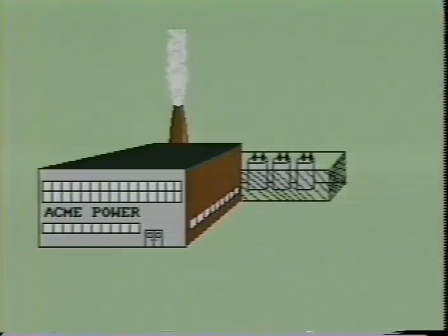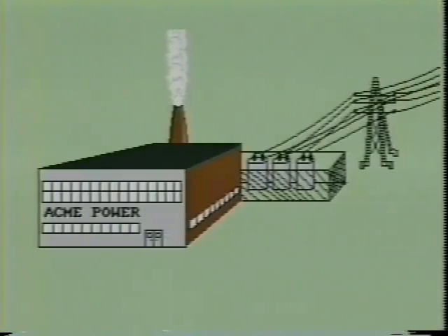For this reason, this high AC voltage is fed into large transformers to be boosted to an even greater value. These large transformers will boost the 13,800 volts upwards to 150,000 volts or even greater. This high AC voltage is then transmitted over the high-tension transmission lines for distances ranging up to several hundreds of miles.